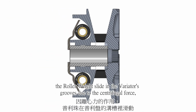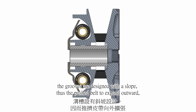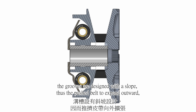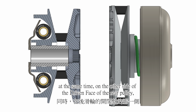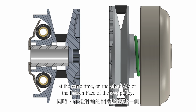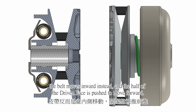the roller weights slide in the variator's grooves due to centrifugal force. The grooves are designed with a slope, thus pushing the belt to expand outward, because the total length of the belt is constant. At the same time, on the other side, at the driven face of the rear pulley, the belt moves inward instead, and the half of the driven face is pushed to move forward.